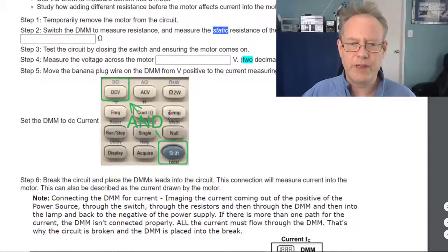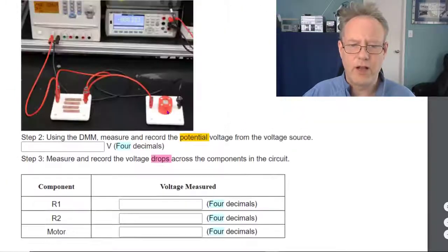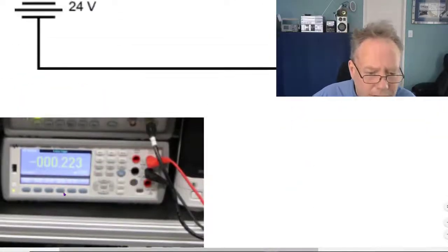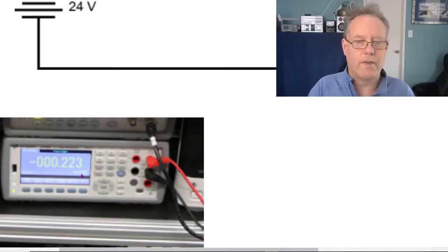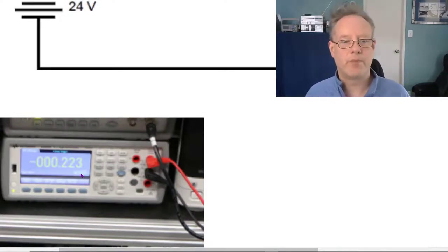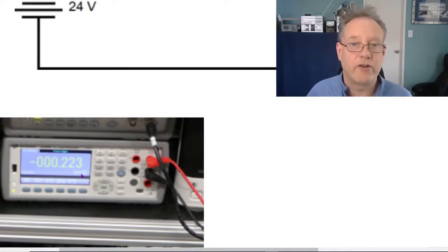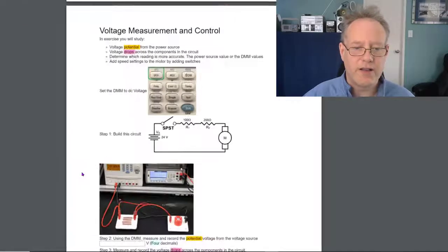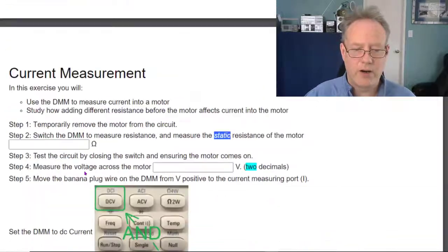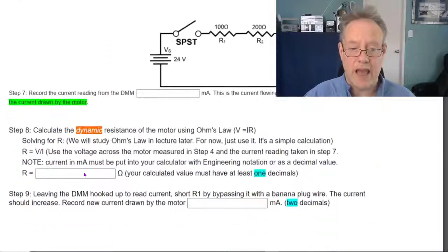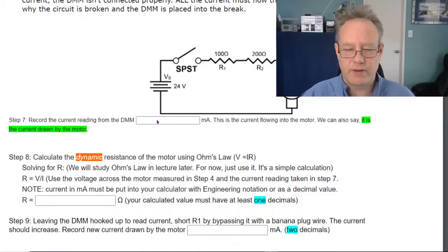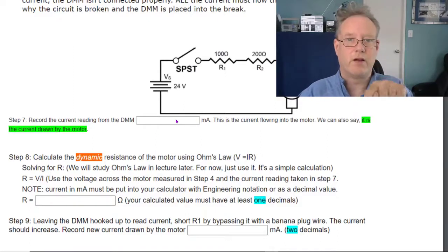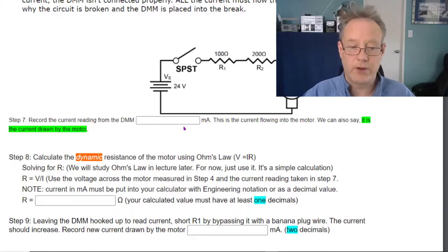Now the meter itself, let me go back up to a picture of the meter over here. This meter is reading millivolts DC. It's set in millivolts. The number that's on there is in millivolts. If I had 200 millivolts, it's 0.2 volts. But if it's reading millivolts, it'll say 200. It won't say 0.2. My point here is that milliamps is kind of the same thing. Whatever the meter is reading, it will actually give you milliamps. So record the reading of the meter in milliamps. Just put the number in the meter right there, and that number is milliamps. I've already put the unit here for you.